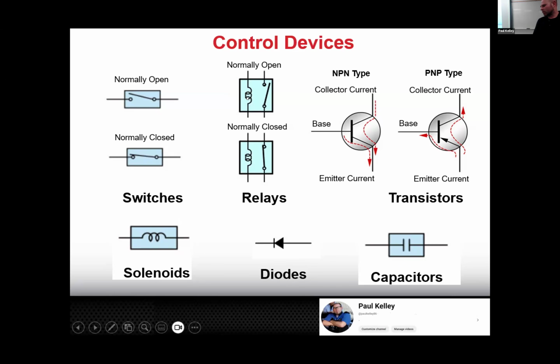So if I were to extract this relay and throw it into a diagram, maybe what we do is we give 12 volts to the coil and we give 12 volts to the switch side. And then on the switch side, it goes down to the fuel pump to give the fuel pump power. But on the control side, maybe we wire this into the ECM, and all the ECM has to do is give ground or not give ground. If the ECM gives ground, this goes on, and it makes it switch over, and it powers the fuel pump.